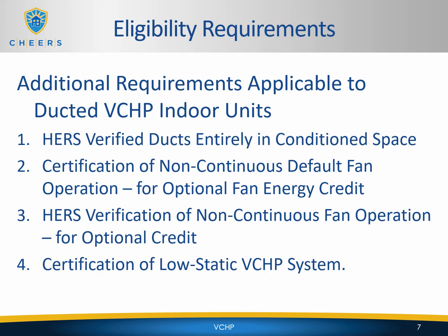So now let's look at those additional requirements that are applicable only to ducted VCHP indoor units. So first we have HERS verified ducts entirely in conditioned space, a certification of non-continuous default fan operation. This is for an optional fan energy credit. It is not HERS verified. And then we do have a HERS verification of non-continuous fan operation, which again is an optional credit. So you may or may not see these. Only one of them is HERS verified.